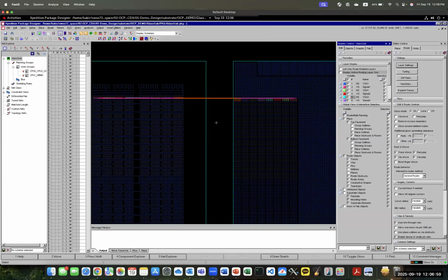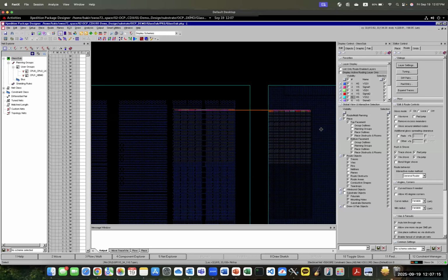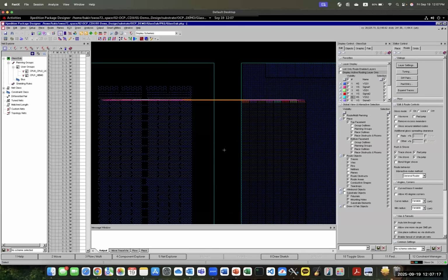If the very long routes, which are back to back, don't work, we may have to flip the HBM5 on the CPU side, such that we connect front to back and back to front. But we'll see how the signal integrity looks, and crosstalk and things like that.